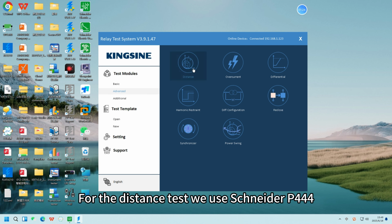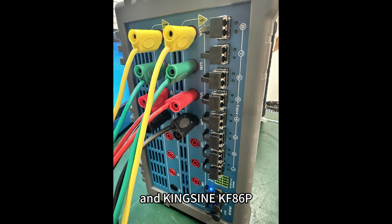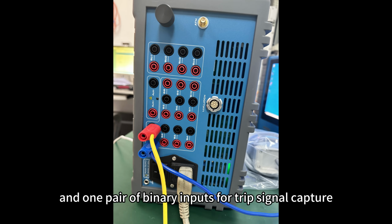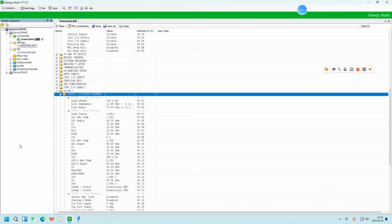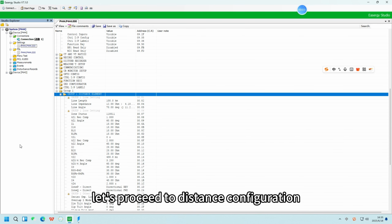For the distance test, we use Schneider P444 and Kingsine KF86P. We connect one group of voltage and current channels, and one pair of binary inputs for trip signal capture. The very first step we have to do is to upload the setting value from the protection relay. Now that hardware connections are established, let's proceed to distance configuration.